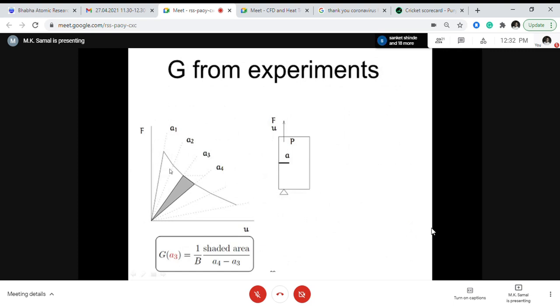Now once the crack propagates, you can see the load will start reducing. So for crack a2 the point is here. Then when the crack is propagating, the load is reduced. Here I am applying a displacement control. Because if I use load control and increase the load, it will become unstable. It will just fail here. The curve will not go down. You must understand this, it is very important. So what I am doing is actually applying a displacement.